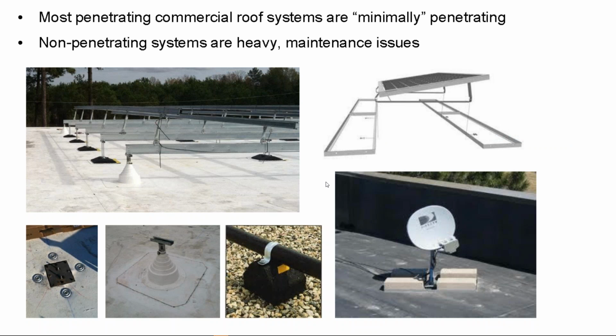I greatly prefer positively attached systems in high seismic zones. They're also important because, again, loose concrete bouncing around on a roof in an earthquake is not a good idea.